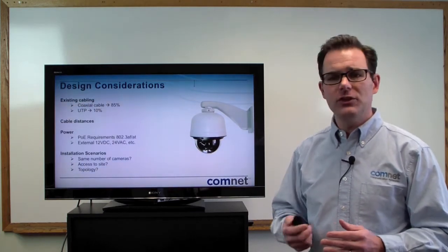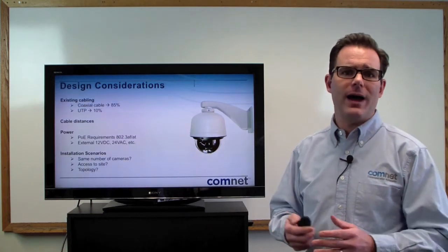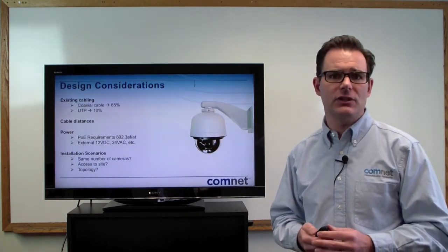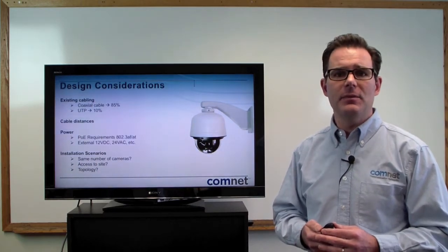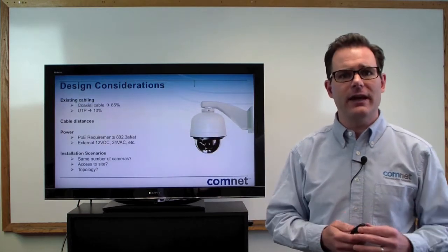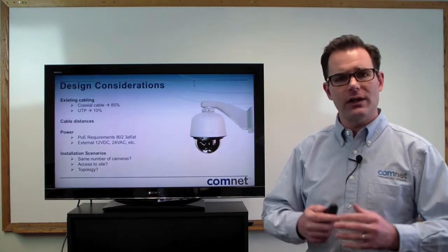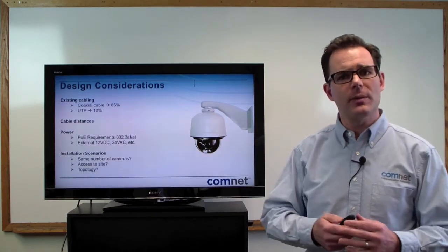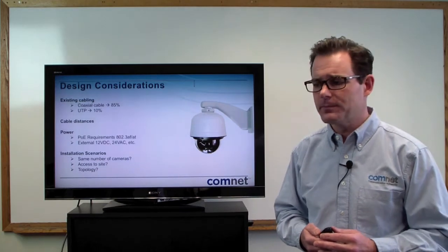Then when you take a look at the power requirements, are your new devices PoE, or do they also have additional powering capabilities such as 12 volts DC or 24 volts AC? And if you're able to utilize existing power infrastructure, that may be an advantage. But also, with new retrofit scenarios, you can remove all external power requirements and power it all with a pass-through PoE. And that might be a significant advantage in a number of ways that we'll get to.